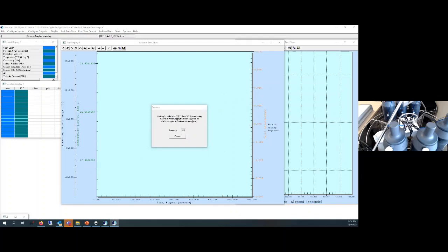Okay, first thing it's going to do is say launch CSAVE acquisition, and then you may have seen it briefly. It says initializing the water sampler. If you don't have the correct COM port set up for your water sampler, or you don't have a serial cable connected to the carousel data connector on the back of your deck unit, it's going to give you an error saying failed to initialize water sampler. In this case, everything is connected properly, so now it's just waiting for CTD data.